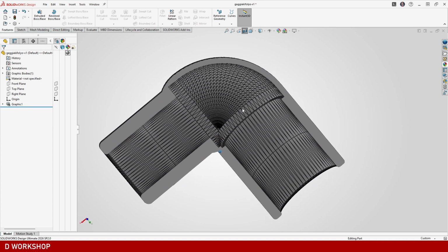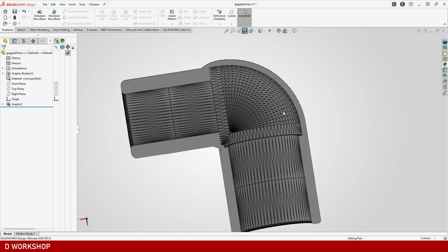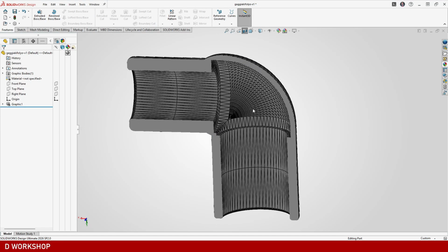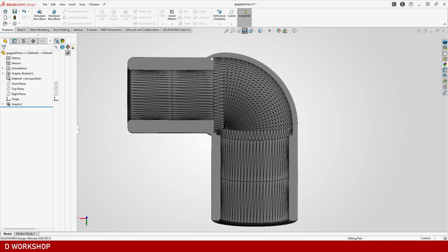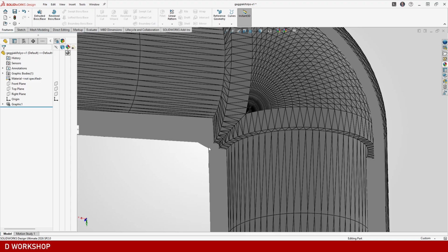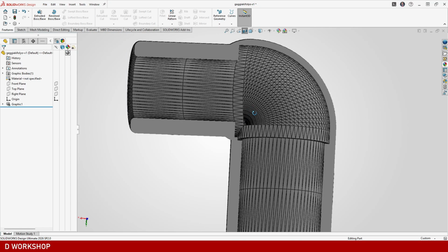What I notice immediately is this strange internal cut, which is absolutely wrong. There is no reason you need a smaller thickness here. You can see that the person who did the model actually doesn't know modeling very well, and this is resulting in this very thin area, the place where my part was actually broken.